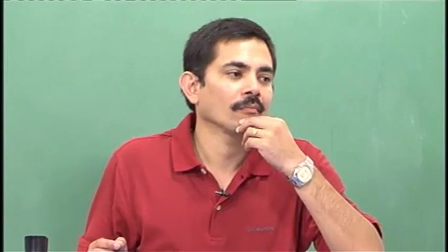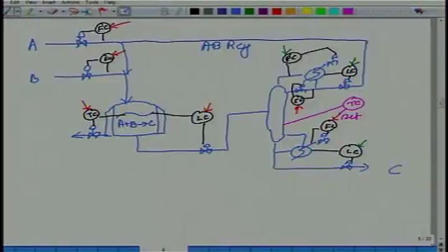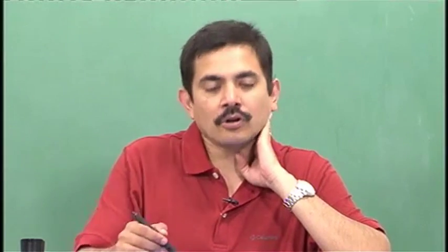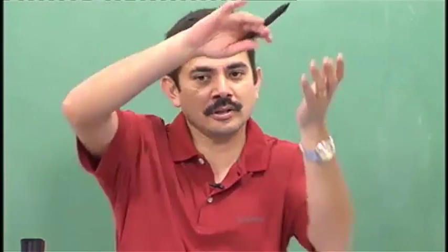yeah. So what will happen to the steam? You have excess of A being put in, that is, the temperature controller is not allowing that excess A to drop down the bottoms. What is the controller doing? It is essentially increasing the steam, yeah. There will definitely come a stage where you cannot increase the steam anymore, okay. So let us say then the temperature controller has been increasing the steam, or maybe the column gets flooded because you are boiling up so much. Your boil up is increasing, now the liquid cannot drop down, the column is flooded, okay.